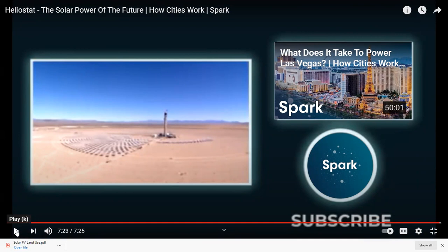They get that stuff heated up, and they get so much energy stored in it that even after the sun goes down, they can still run the plant, depending on load, for probably 3-4 hours into the evening. That's when there's still a lot of peak load out there. So they can continue to operate even after they've lost their input energy, because there's so much energy stored in that salt.